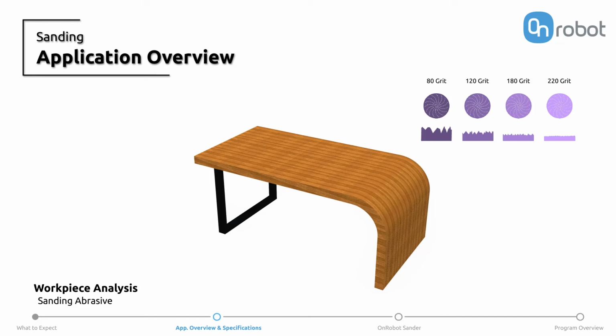Remember to always start the sanding process with a coarse enough sandpaper grit to remove the imperfections quickly. Then continue using finer grits to remove the scratches from the previous one used. The final grit will bring the surface to the desired smoothness. There is no fixed rule for how to progress through the grits, but it is important to avoid skipping a grit, as a coarse one could leave deep scratches that successive finer grits might not be able to remove.